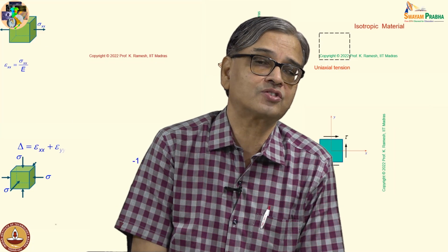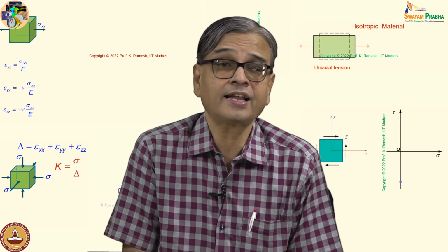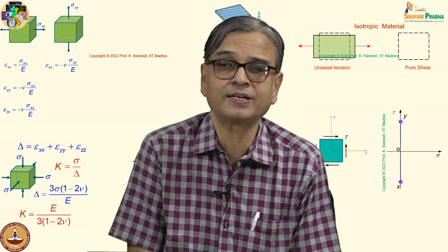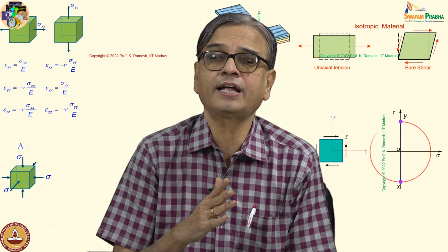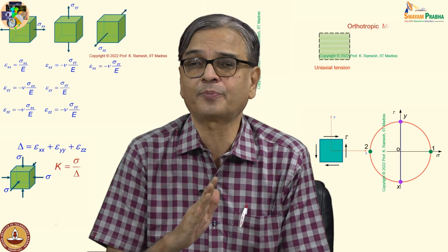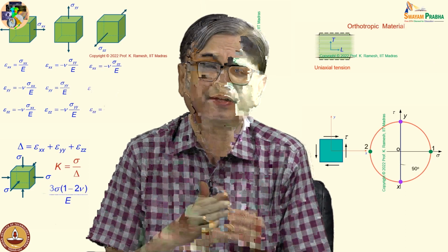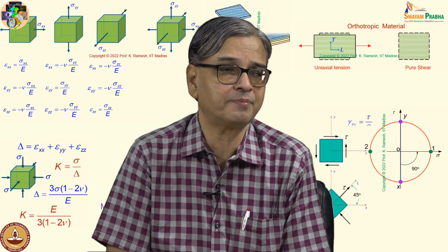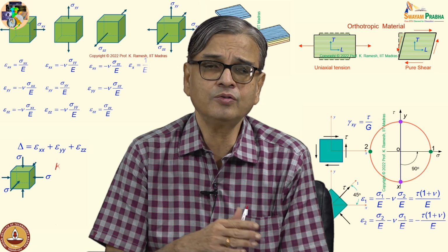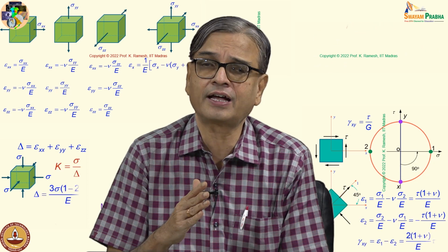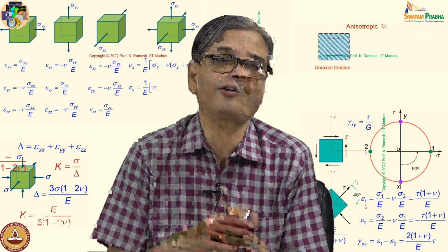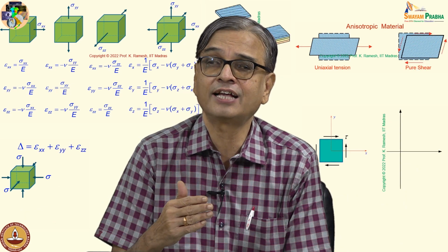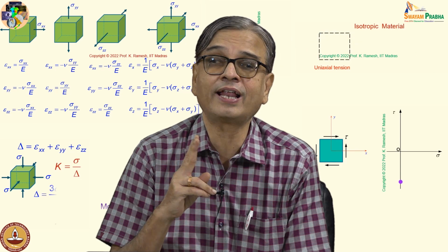So in this class, we looked at the interrelationship between modulus and shear modulus. We also looked at what the limiting values of the Poisson's ratio are, and where the ratio is used, such as in the medical industry. Then we have also seen that in the case of an anisotropic material, you need 21 elastic constants, whereas an isotropic material requires only 2 elastic constants.